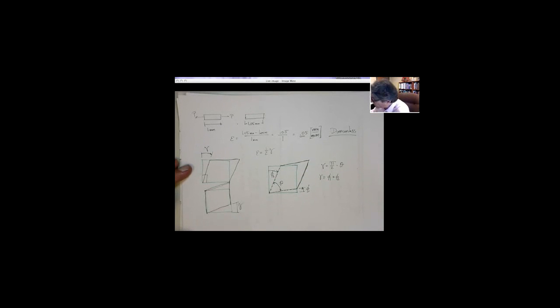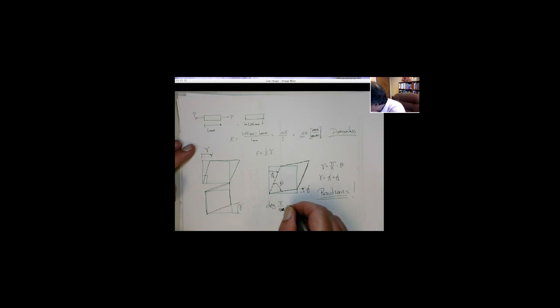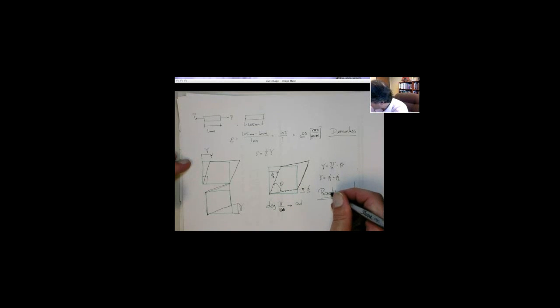And now, a couple things to note. One is, when we talk about shear strains, we're talking about angle changes, but they're in radians. Very important. Radians. Not degrees. You always have to convert: a degree times pi over 180 gives you radians.